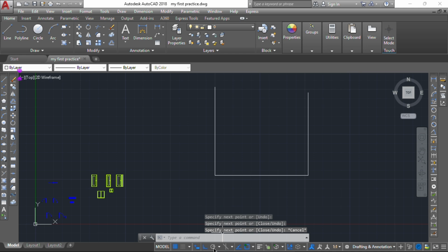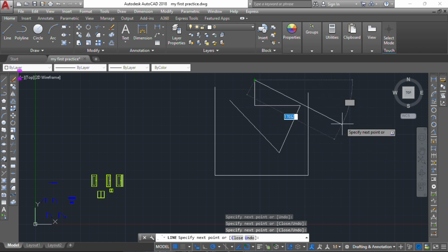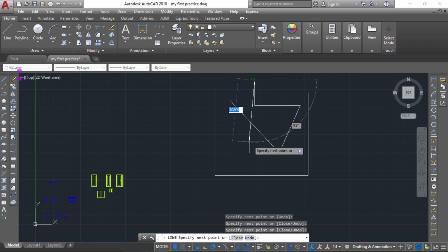But if you switch it off and come here to work alternatively, if I switch on the polar, auto will go off. Now that I've selected my polar, let me switch it on. It's indicating that I can draw an angular line. I can draw lines at various angles, not necessarily vertical or horizontal, and I can bring my cursor to any degree here. As I'm drawing a straight line, it's showing me a continuous green dotted line, indicating my line is straight. If I'm not having that, definitely I'm drawing an inclined line with an angle.